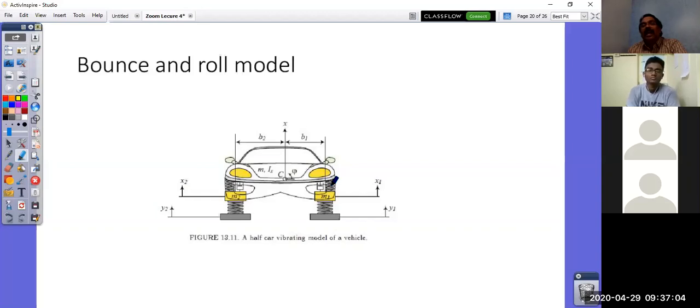And this model can be excited by a regular sinusoidal excitation, and you can look at it. See, I know this sprung mass frequency is near 1 Hertz for the roll. I will excite this so that there is one bounce and rebound like that. Then I can make this roll. So when I make this roll, the amplitude of vibration is the measure that is going to tune my suspension design. So that is how we can work on the design of suspension.